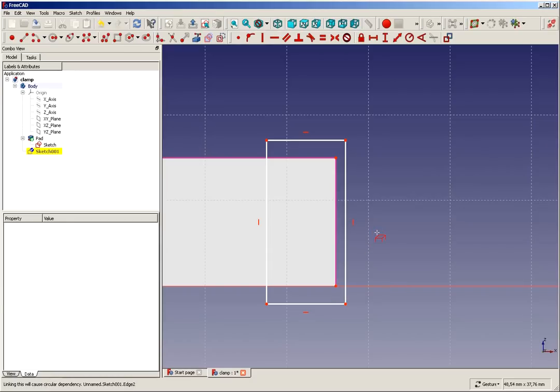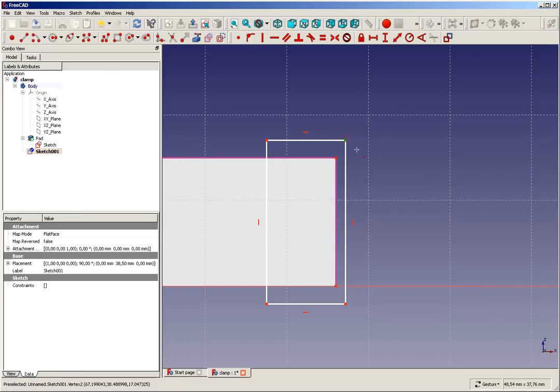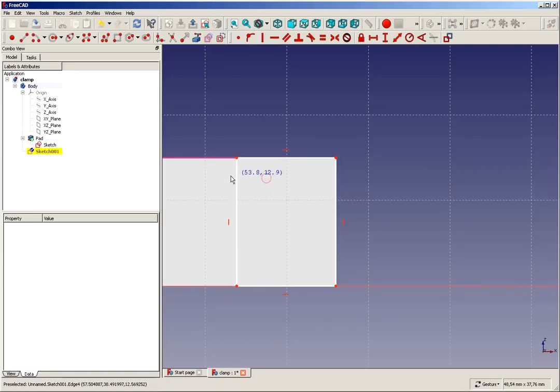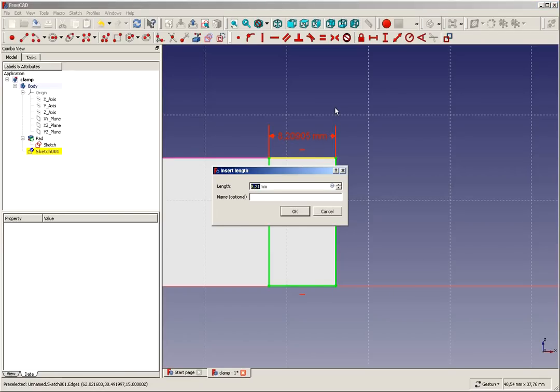That's what we need. We don't need anything more. So just keep in mind, for later designs it makes sense to learn about techniques that are better than selecting any vertices, any lines that have been derived from the previous feature. This pad is called a feature. So as we have these 2 points now, we can carry on and just constrain these over each other, and we need one constraint, which is a length, and that length is 10 millimeters.